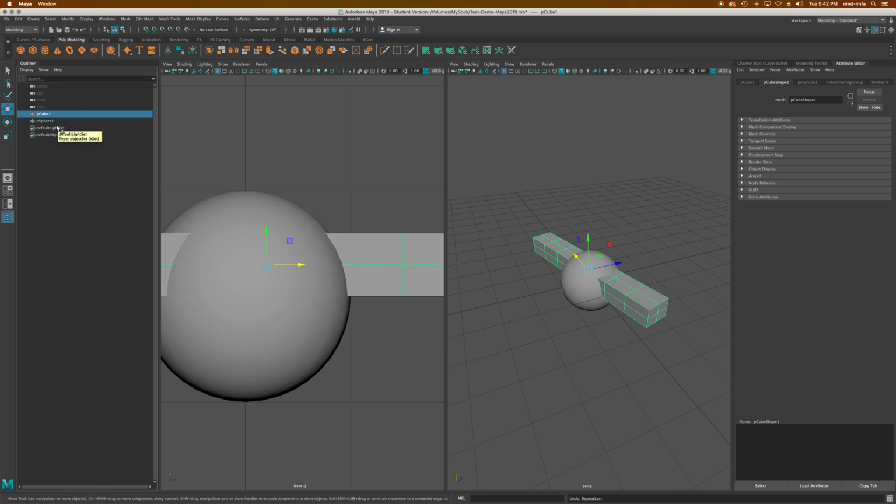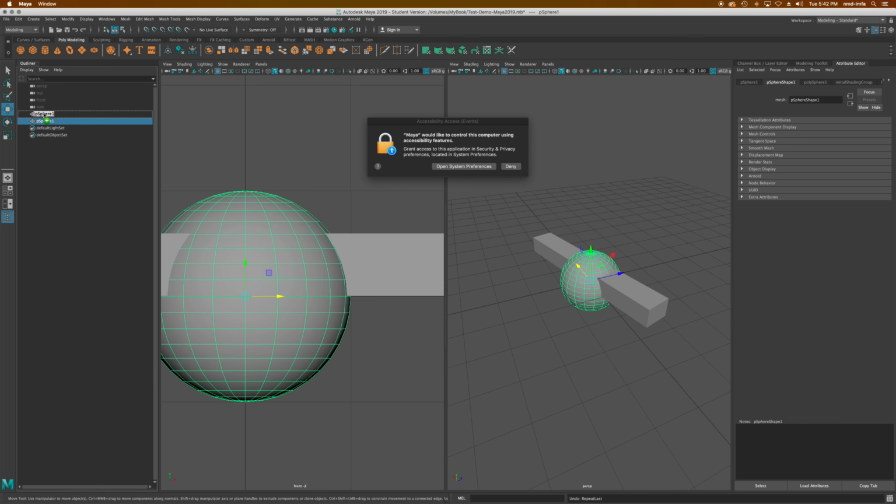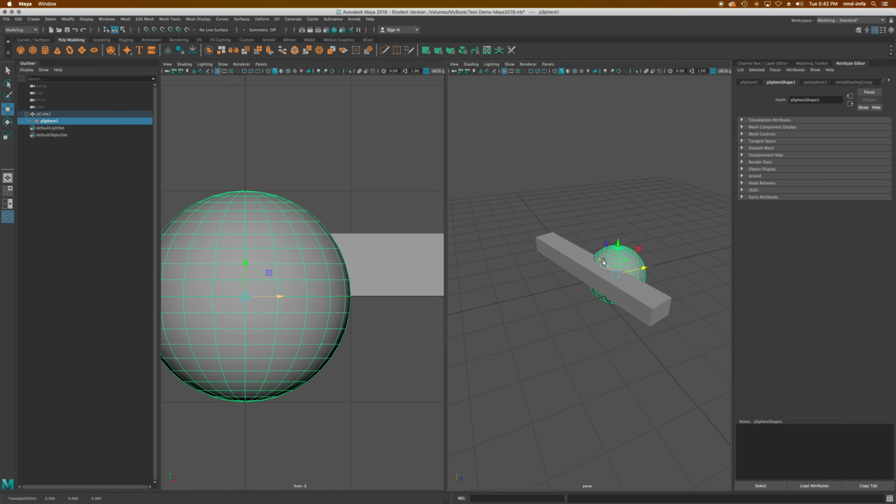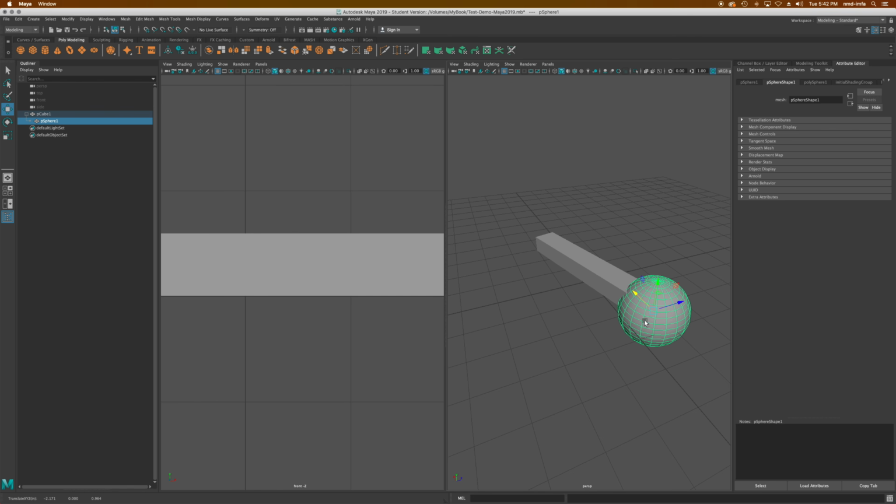You can also middle click an object and drag it onto another object, and then it becomes a child of that object, which is kind of cool. So if I choose cube now, it'll choose the cube and the sphere together, and you'll see as I move it, they move together as one. But then I could just choose the sphere and still have the sphere as the child of the parent. Maybe this was the joint of an arm or something I was working on, right? And I wanted to be able to move the whole thing together. Now it's easy because they can be assigned together like that.